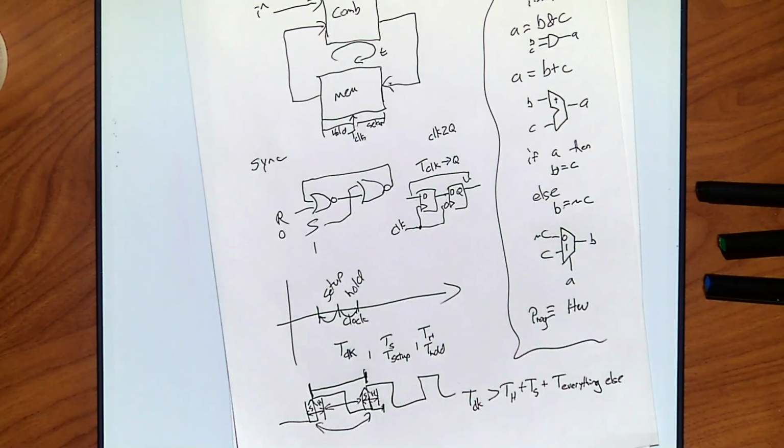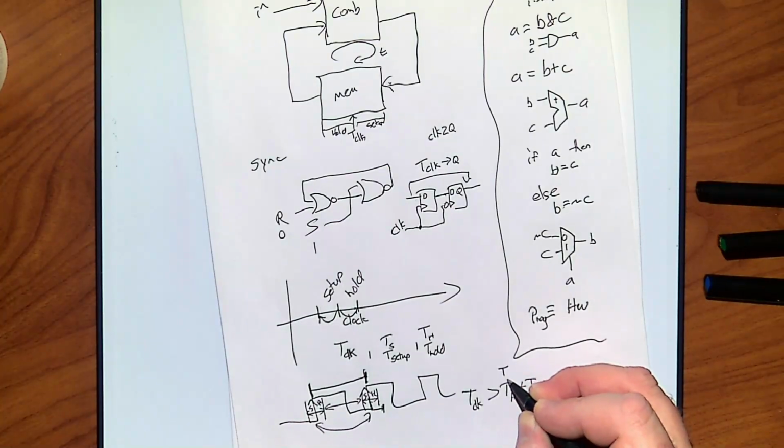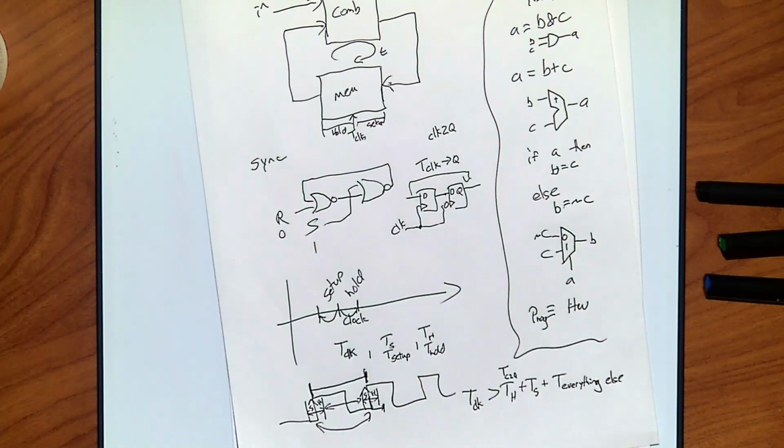Typically you will just report T clock to Q in your testing. I'm just going to use an abbreviation, C to Q, clock to Q. Clock to Q and hold overlap each other. Clock to Q is usually bigger, so oftentimes we will just dump hold and replace it.